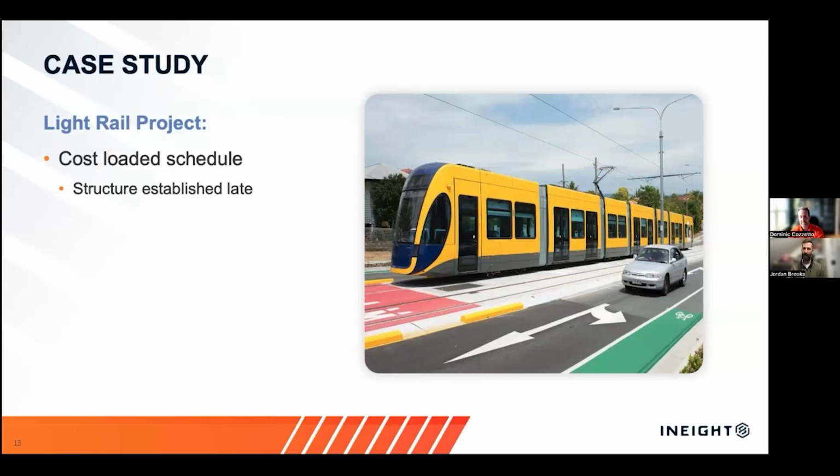It was a pay by schedule type of job. So we submitted a schedule that was cost loaded. The owner would say yes or no, and based on the percent complete and the dollars of actual cost in that schedule is what we would get paid on a monthly basis. So you can imagine with it being cost loaded, pay by schedule, the person who developed the baseline schedule made it very detailed, which happens quite often. Oftentimes when it's pay by schedule and it's going to be cost loaded, you break it down into minute detail so that you can get cost benefits back from submitting a schedule.